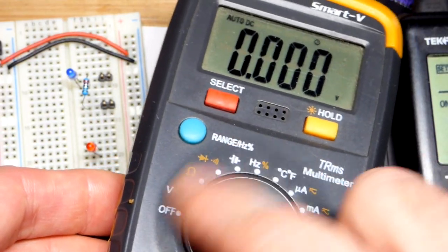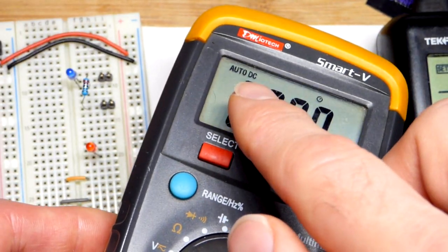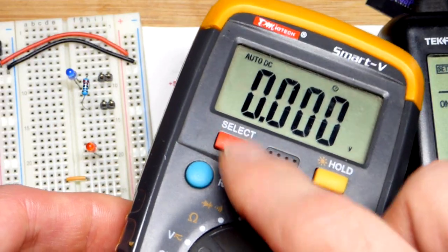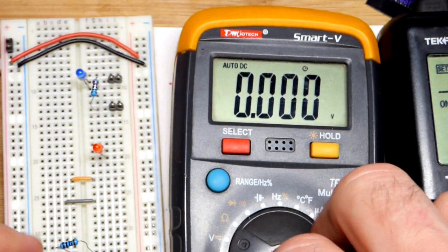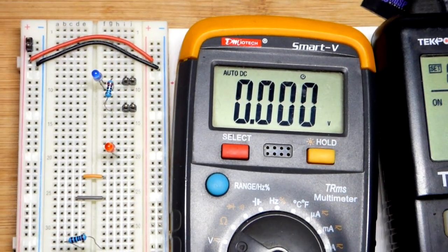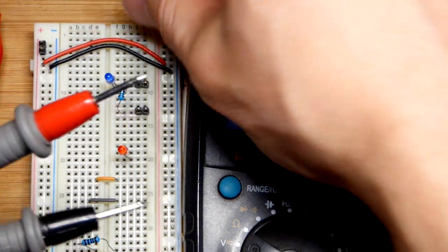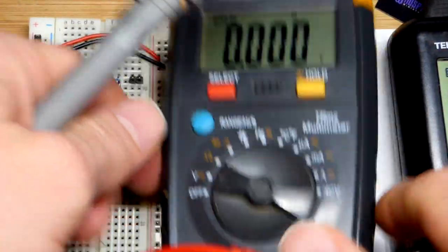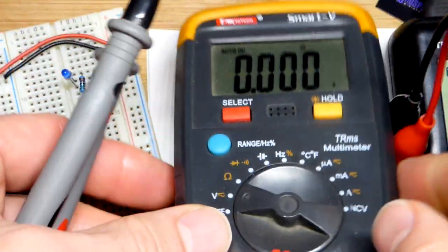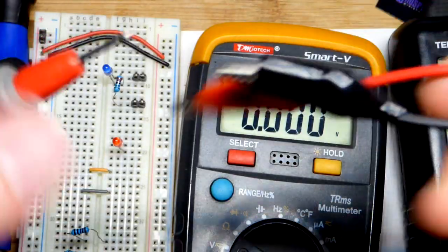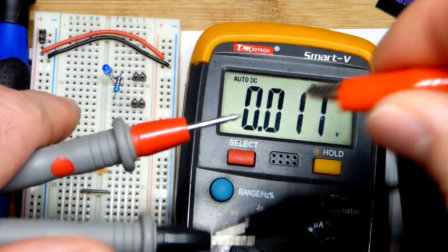If there's numbers alongside the V for voltage, then you would set it to a number higher than what you're going to measure. And right now we are going to measure DC. If we want to measure AC, we would press that. But the vast majority of basic electronics is DC, and so that's just what you can expect to use right there. Pretty straightforward. So I got the probes here, and that's the other end of this. I don't have to move the red probe here for anything other than high current. So the probes generally always stay in the same spot here. Again, I only have to move the red probe for high current, which for basic electronics, you don't even ever have to do.